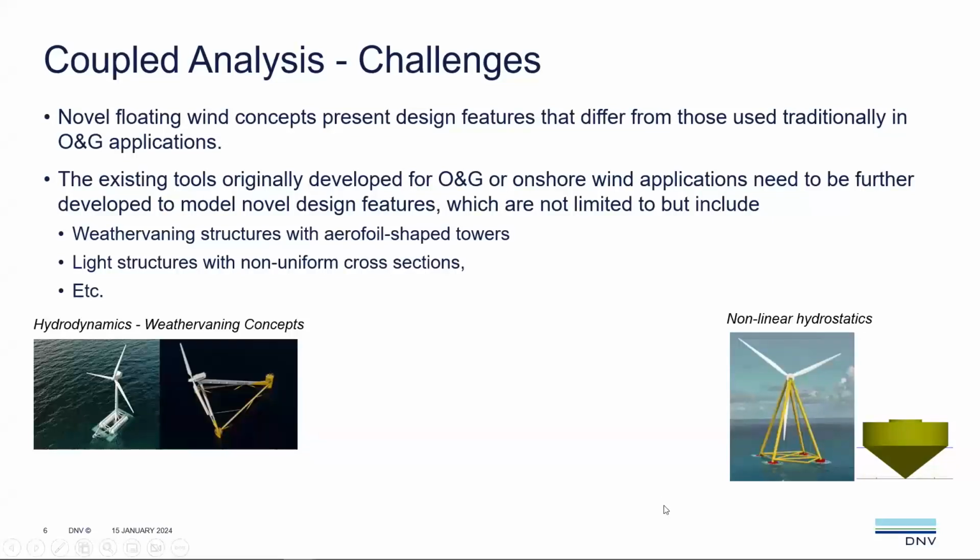Another example of these novel systems is this T-omega design, which includes some non-uniform cross-sectional buoys, which in this case introduce quite a lot of nonlinear hydrostatic loading. This is something that most of these legacy oil and gas tools do not incorporate, and therefore there's a need for further development to be able to represent as accurately as possible the dynamics of these new systems.